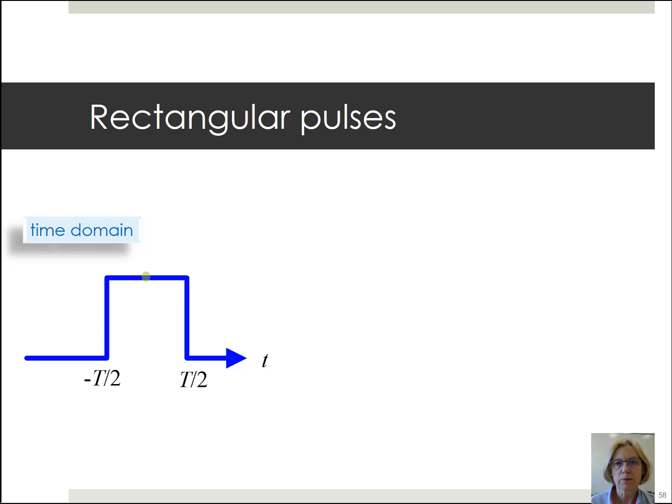Now, if we use a rectangular pulse, that means that when it comes time for the next bit, when we do our sample of what the next bit was, this particular bit will have been 0 at the time when we're sampling to get the next data bit. That means that there will be no intersymbol interference. This symbol in this time frame provides no interference to the next symbol, because when we sample at the next symbol, this previous symbol will have gone to 0.